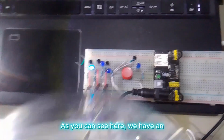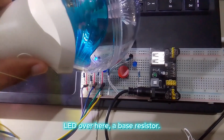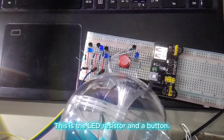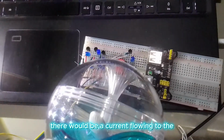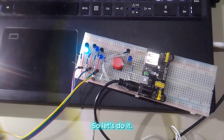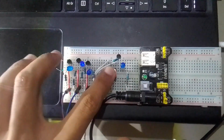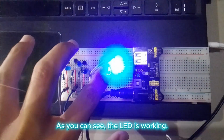As you can see here, we have an LED over here, a base resistor, this is the LED resistor, and a button. If you press this button, there will be a current flowing to the base, which then activates the LED. So let's do it. As you can see, the LED is working.